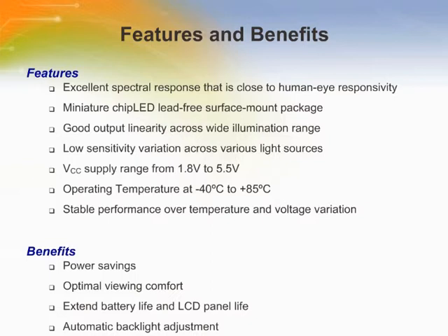The sensors are also designed to significantly reduce power consumption and save battery life in portable and mobile devices by enabling the auto adjustments of the LCD backlight intensity and keypad lighting. Packaged in a miniature chip-led surface mount package, the ALSs also sustain temperature ranges of -40 to +85 degrees centigrade and VCC supplies from 1.8 to 5.5 volts and are RoHS compliant.